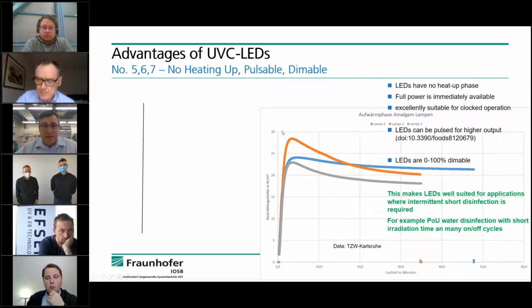You will need at least 3 minutes to get the maximum power. And here we have lamps in water, so you have cooling effects and the power drops. With LEDs, you don't have these effects. Full power is immediately available, so LEDs are suitable for clocked operation. For instance, in a faucet, you can open it, water flows out, the LED is switched on, and if you close it, the LED is switched off immediately.